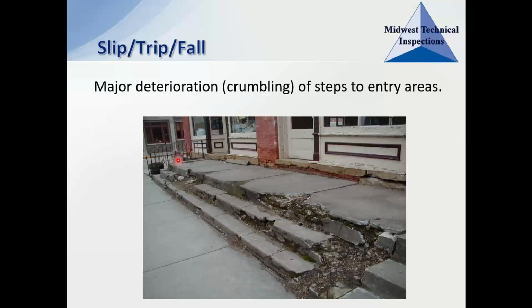So the ideal that we're looking for is these vertical spindles like this, where they're going up and down, and they're spaced no more than 4 inches apart, because the average human head is greater than 4 inches. So if your spindles are every 4 inches or closer, then they're not going to be able to get their head stuck through those between those spindles.